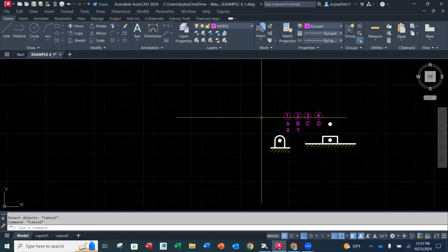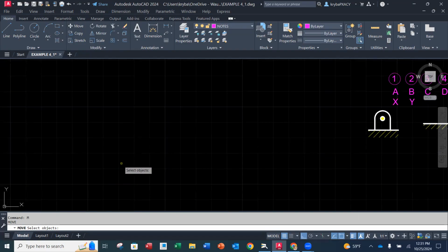Now, I use a lot of quick commands on my keyboard. So M, enter. The space bar is also an enter key for AutoCAD. So if you do M space bar, and that's what I do, it goes into the move command. That's one way that I am more efficient, and that's what I like about AutoCAD: I've used it for many, many years.